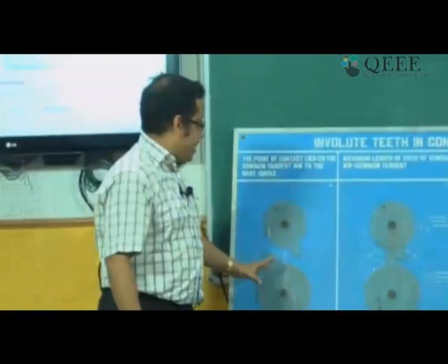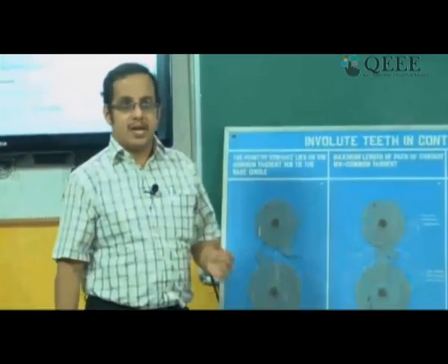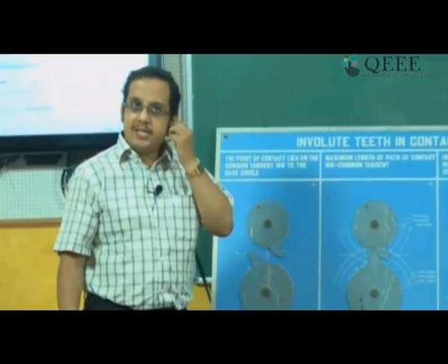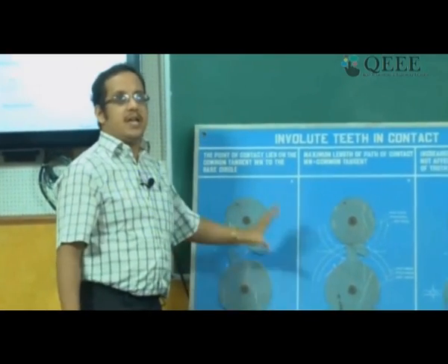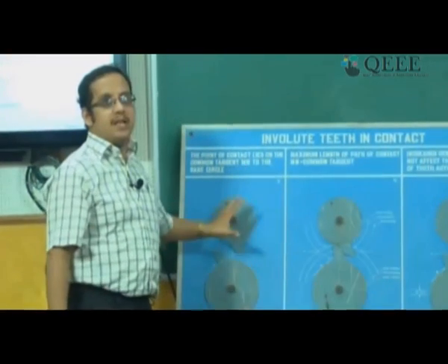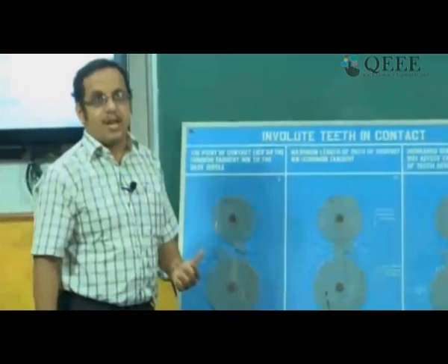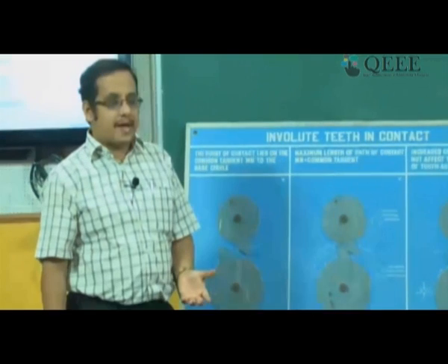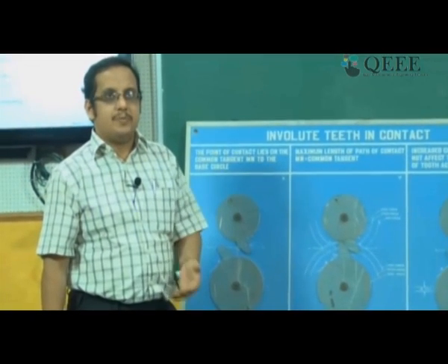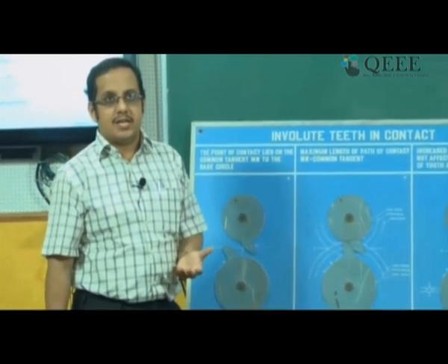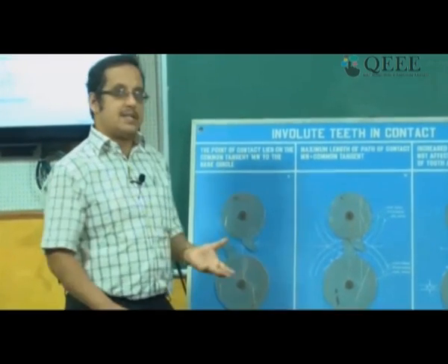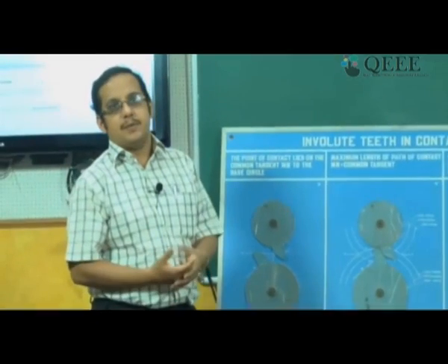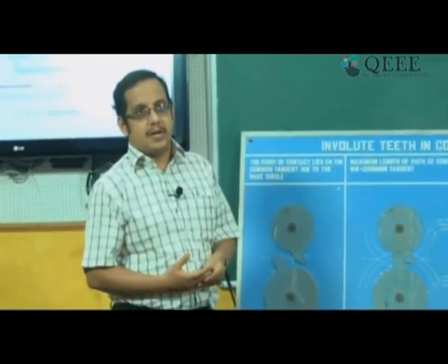But at this point, this demonstration should make it clear to you that this fundamental law of gearing is getting satisfied in this manner. This has been demonstrated through a model, but now we will come back and try to analyze a bit more theoretically, a bit more rigorously, in some geometric fashion, why it is that the involute tooth profile is able to satisfy the fundamental law of gearing.